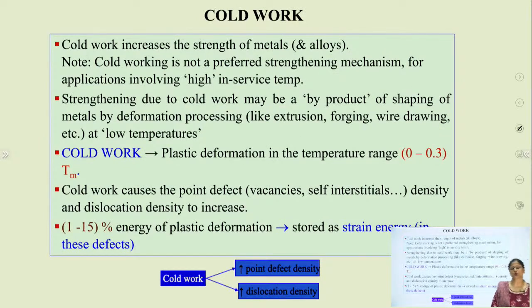So what happens during cold working? During cold working, strength increases, but it is not the preferred strengthening mechanism for applications involving high service temperature. The material used in applications where there are severe temperature conditions, so the cold working material is not preferred in those applications.